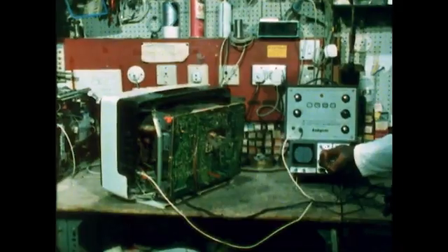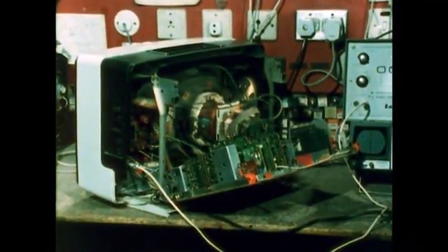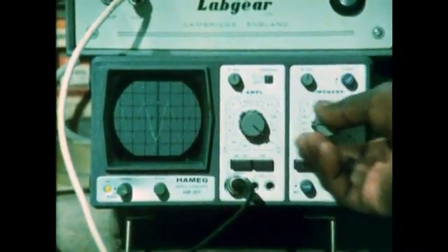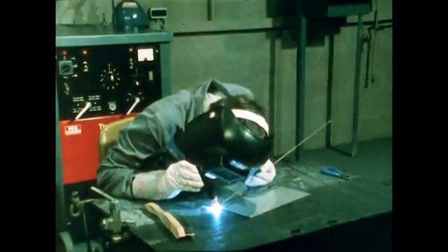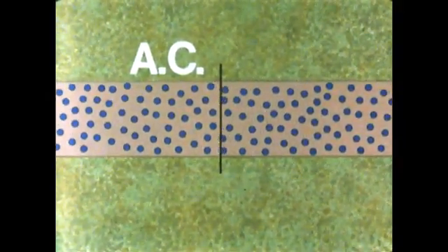There are literally hundreds of bits of electrical equipment requiring a lot of different voltages. And again, if we use AC, we can make use of transformers to produce exactly the right voltage for each piece of equipment. Alternating current, like direct current, is measured in amps, but with a difference. Let's see what the difference is. Take 1 amp DC. When 1 amp flows, a known, very large number of electrons passes a point in 1 second. Well, it's the same for AC, except that the electrons flow past the point in one direction, then reverse and flow past in the other direction.